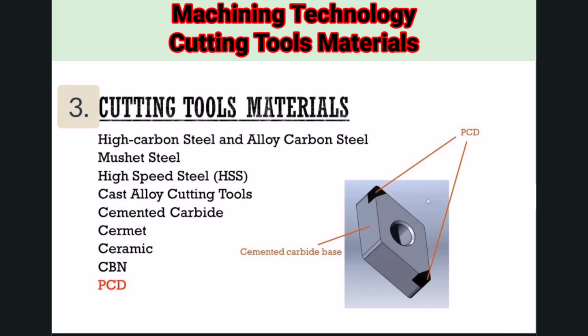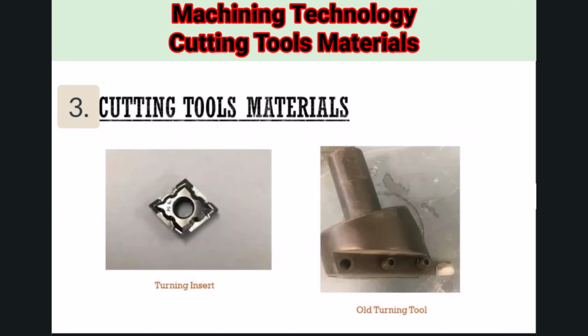Cutting tools get damaged and wear out because of the cutting process. In the past, cutting tools were reshaped and sharpened. However, this is not the case with indexable inserts. As soon as they wear out or get damaged, they are replaced with a new one. Indexable inserts have very tight tolerances, which makes them a favorable choice for CNC machines, and they will be the main focus of the current course.